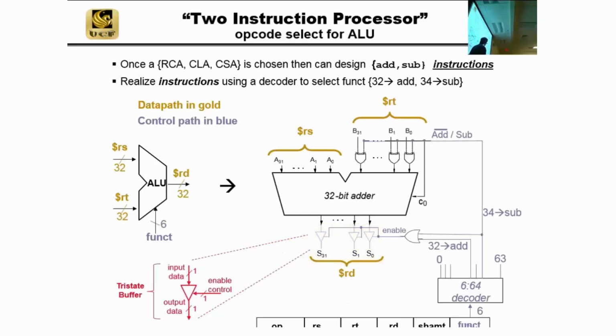So actually what we're going to do is we're going to use this enable line. And here's the function of this tri-state buffer. Whenever we see this triangle, it's telling us what the circuit symbol does. Input goes to output. It's shooting bits just in this direction, but there's a gate, like a transistor we talked about. Okay, so tri-state buffer.